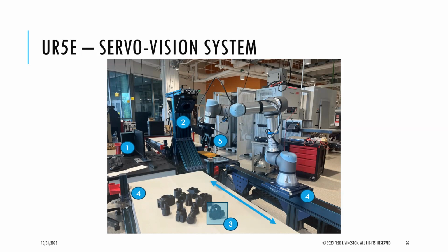That is going in the positive direction. So I'm here now, end effector to the camera, still positive. And then camera to the object. And since they are positive, this is just going to become a dot product there. And then you're left with a 4x4 matrix with your rotation component and then your X, Y, and Z, the location there.